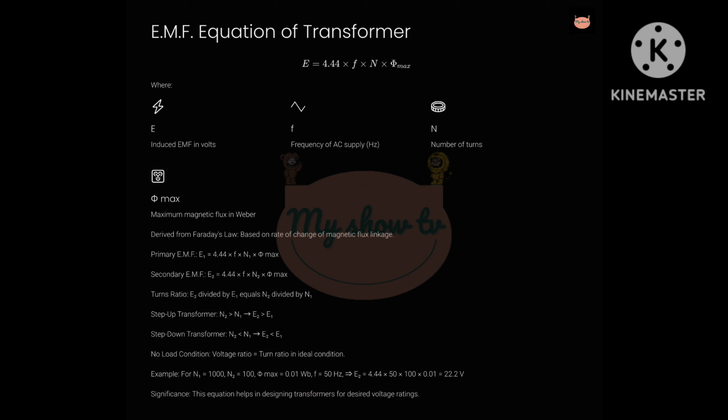Let's now discuss the e.m.f equation, which helps us calculate the induced voltage in the transformer windings. 1. The standard e.m.f equation of a transformer is E equals 4.44 times f times N times phi max, where E equals RMS value of induced e.m.f, f equals frequency of supply in Hz, N equals number of turns in the coil, phi max equals maximum flux in Webers. 2.